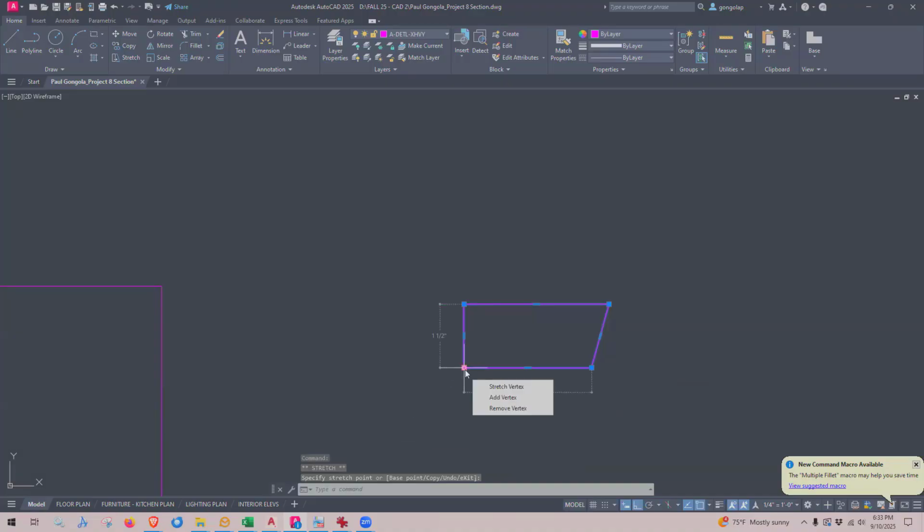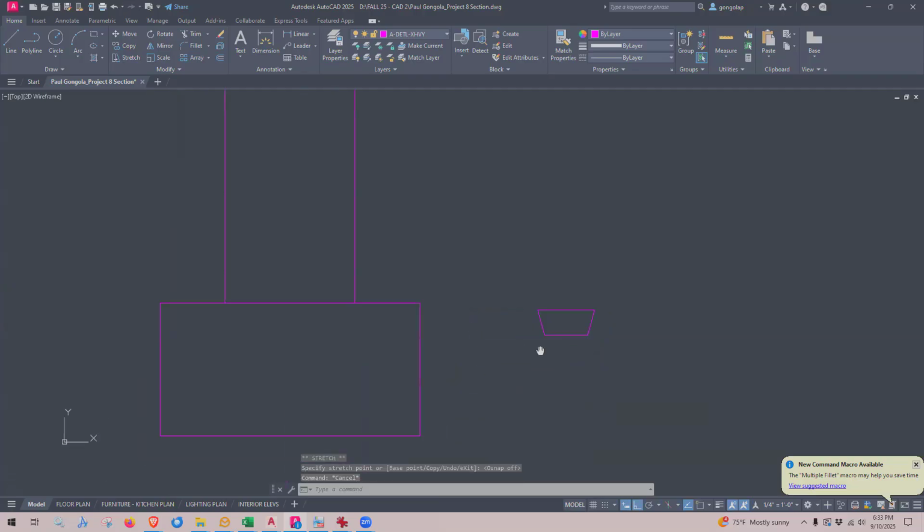And then this side, and if you are finding that you're snapping, turn your O snaps off. That can sometimes help you here. And just come in like that. It's not exact, but it doesn't need to be. That is all that we're going to need to do for that.